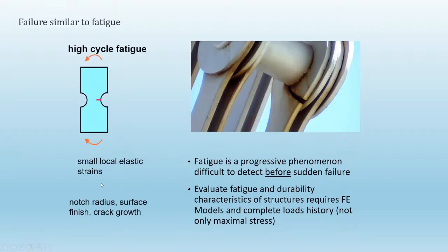Fatigue, most of you should probably know this, but we typically start with testing. There's a small local elastic strain that builds up at the key areas, and this will eventually cause a crack to grow. And as we keep cycling, pulling on this bar repeatedly, the crack will grow and eventually cut across. So fatigue is also a progressive phenomenon.